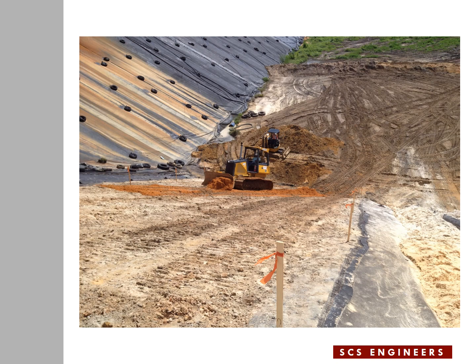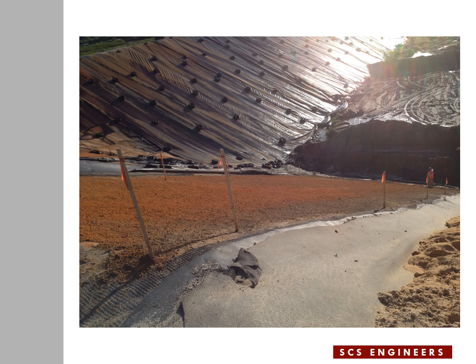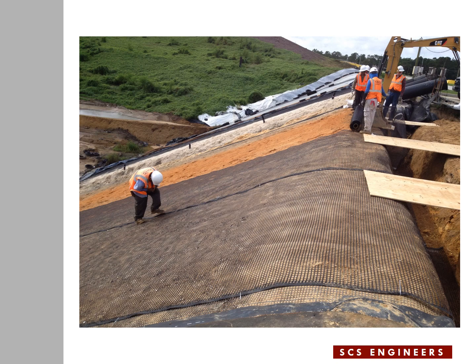They start with bringing soil, pushing soil over the slope in order to regrade the slope for installation of the geosynthetics. In this slide, the soil is already placed and graded, and the area is ready to receive the first geosynthetic layer, which is a geogrid. Here the geogrid installation has commenced. To the left side is the 2-to-1 slope going down, and geogrid is extended over the 2-to-1 slope. To the right side you see a deep anchor trench for the geogrid.